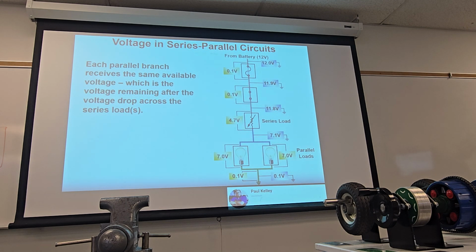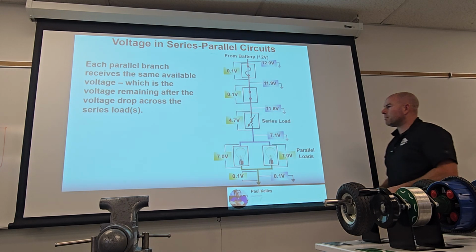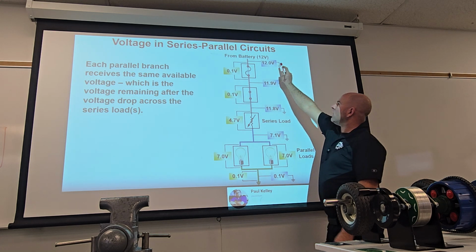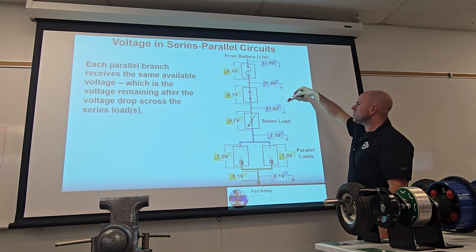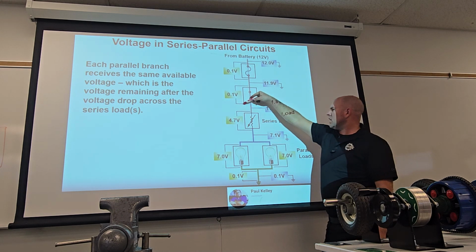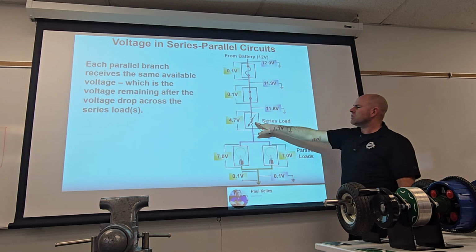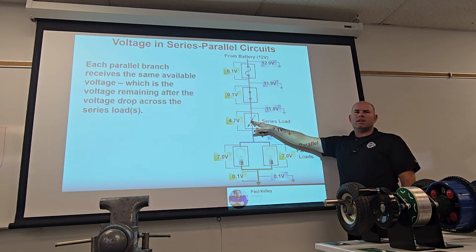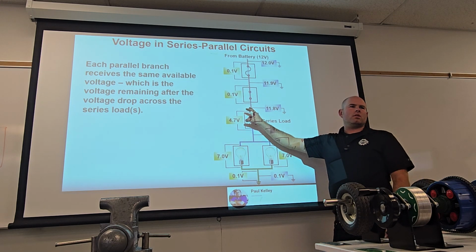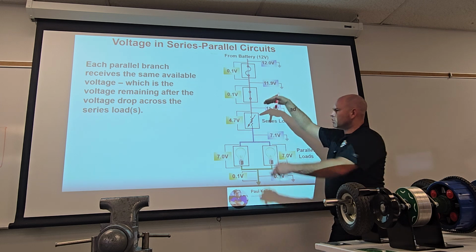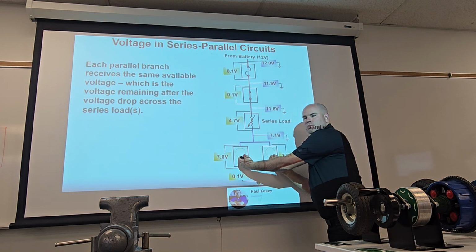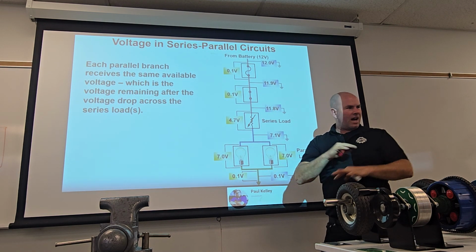Okay, so if you were to look, let's say the voltage drop, for example, you got 12 at the source, you might drop a tiny little bit at the fuse, you might drop a tiny little bit at the switch, which is now closed. How much do you think we should drop at this? Not a tiny bit, right? That's a load. But should we drop all 12 volts though? Because if you drop all 12 volts here, what is with these bulbs? They'll be out, right?